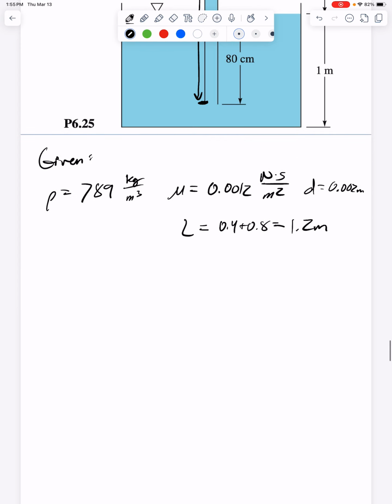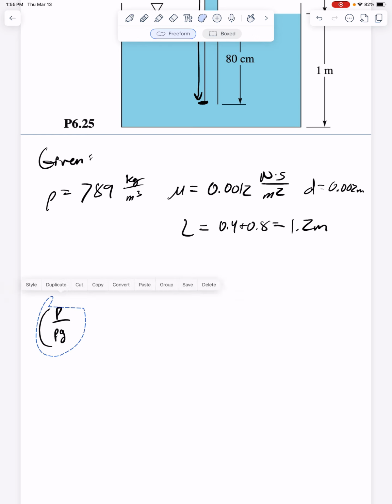Okay, we're trying to solve for flow rate. Flow rate we can obtain through many ways, but I guess finding velocity is probably one of them, right? Where can we find velocity? Let's look at the energy equation. And I probably should mention, given barely any information, let's assume laminar flow too.